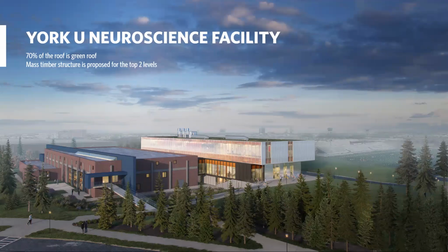The overall building design is very energy efficient and sustainable. A pre-grown modular green roof system covers almost 70% of the roof area. As you know, having a certain percentage of green roof is a requirement in the city of Toronto. Our team really maximized it to address the stormwater management requirements as well.